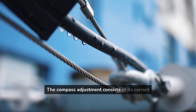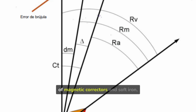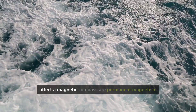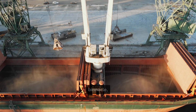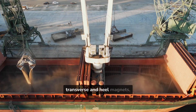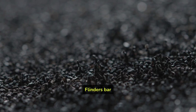The compass adjustment consists of its correct installation, either in or near a binnacle, of magnetic correctors and soft iron, so that their effects are equal and opposite to those of the ship's magnetic material, thus reducing deviations. The magnetic conditions on a ship that affect a magnetic compass are permanent magnetism and induced magnetism. In a nautical compass installed in a binnacle, permanent magnetism is corrected with longitudinal, transverse, and heel magnets, and induced magnetism is corrected with the spheres and Flinders bar.